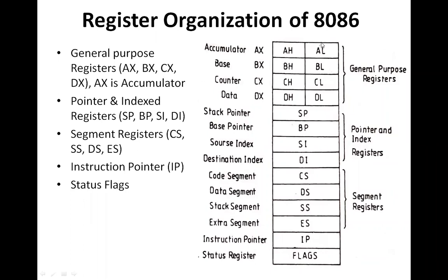processor. So what we used to do, the memory is managed in the form of segmentation. Every memory of 1 megabyte is divided into 16 sections, and each section is of 64 kilobyte. So 16 sections, and each section is of 64 kilobyte. Total capacity of the memory will become 1 megabyte. So individual sections are known as segment. That is why we use the concept of memory segmentation.